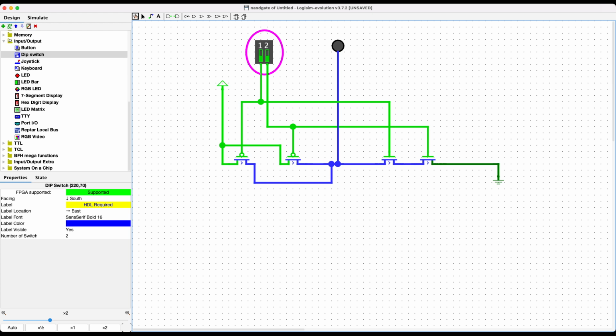Okay, so every time I have a pair of NMOSs in series, I have a complementary set of PMOSs in parallel. And if I flipped this and had NMOSs in parallel, I'd put the PMOSs in series. Okay, so that's another sense in which I say complementary. Okay, because they're in sort of opposite arrangements. Now, what about if I flipped this and I put the two PMOSs in series and the two NMOSs in parallel? We'd get something different, right? What do you think we'd get if we did that?